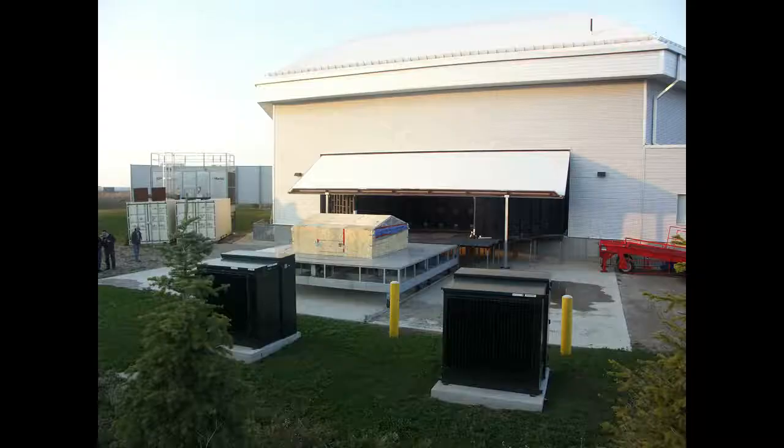Pictured here is the outdoor testing setup at the Windy facility. The 3-dimensional linear contraction, observed in front of the test specimen, is used to increase the wind speed produced by the bank of 60 fans just inside the wind tunnel. The garage doors on either side of the building are open such that wind flows through the tunnel in an open circuit configuration. One of these 2 garage doors forms the upper portion of the contraction.